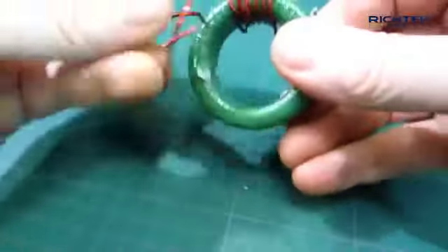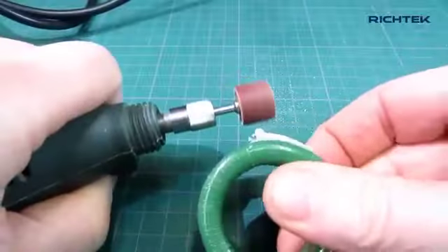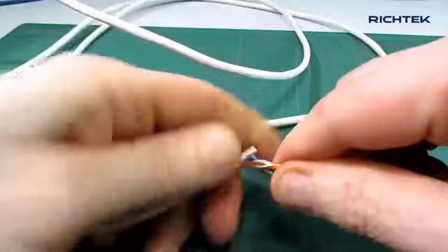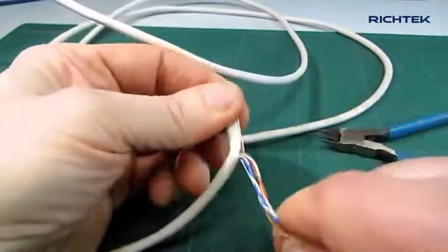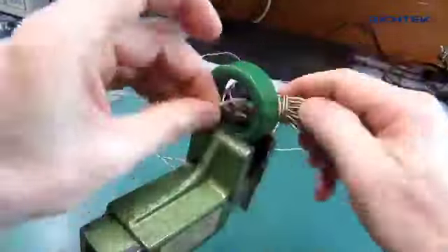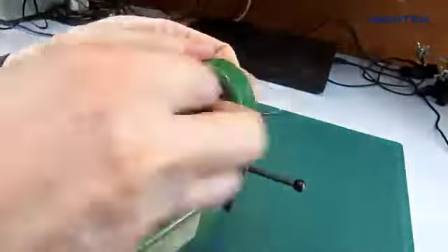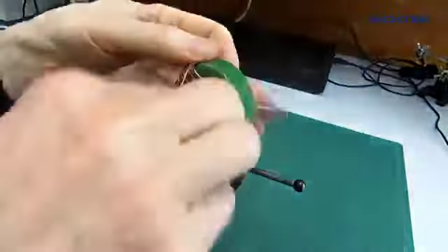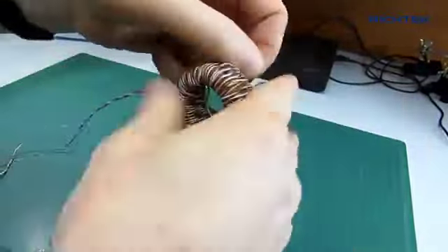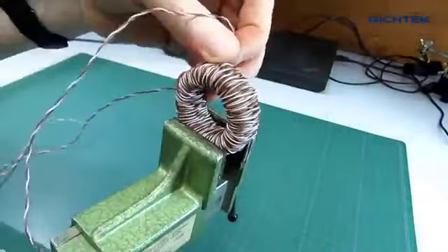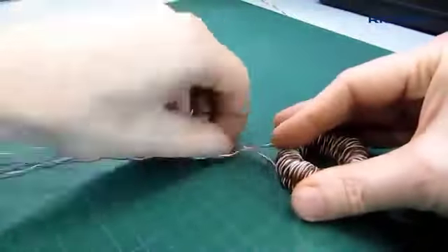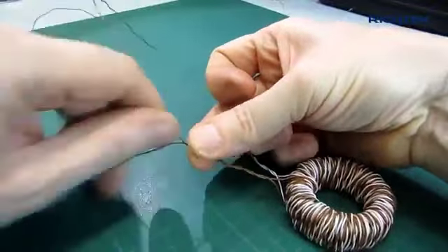First, remove the plastic and the wires. For the windings, I used a twisted pair from a Cat5 Ethernet cable. For this transformer, I needed around 7.5 meters of wire. Start in the middle of the wire and start winding one end to fill the complete core. Place the windings tight. Then start the other wire end and wind the second layer, finishing close to the previously finished winding end. Now separate the twisted wire ends and then twist the wires with the same color to form the primary and secondary winding.